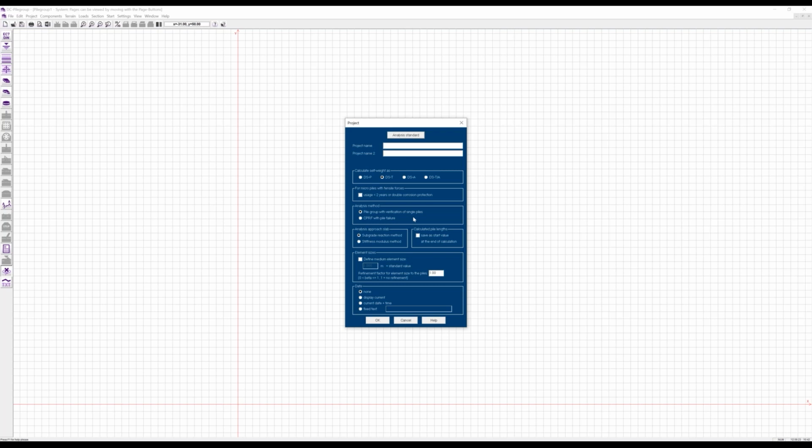But especially for combined pile and raft foundations, we have a second method to calculate, which is called the method with pile failure, which means that the piles might punch into the soil. They have their maximum characteristic resistance, maximum characteristic load for the pile resistance. And if the piles are punching into the soil, there will be more load going to the elastic bedding under the slab. So with a larger deformation, we can transfer more load from the complete construction into the ground.